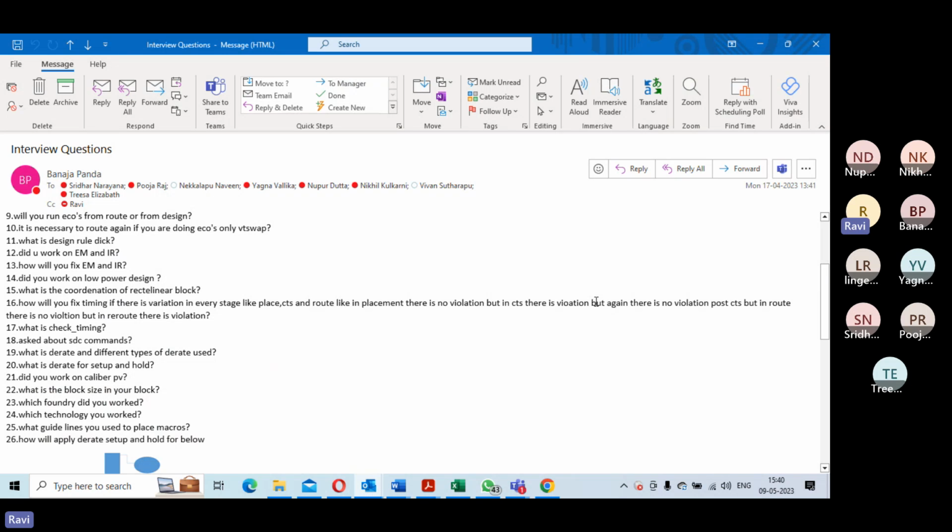So that is why you add additional uncertainty, either in terms of your set clock uncertainty. That's one technique. Second, you can use cell derating. You can use route derating. All these capture the variations because of your route. Similarly, variation is not only in ICC, it could be post route, in your timing tool, the way it sees things would be different, with all the crosstalk, etc. You will factor them in by adding uncertainties either to your frequency or to the deratings of your cells and nets. So that's the way you will address it. Is it clear?